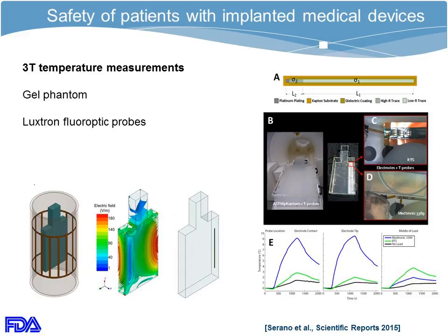It provides an example of how we do that by combining, again, computational models, this is a model of a phantom in a coil with the MRI, and experimental measurements. Computational models by themselves are pretty much useless unless they are somewhat verified and validated against experimental measurements, with a given uncertainty analysis associated with both the numerical simulations and the measurements. And we're working on what the parameters are, and how you can do a validation of a numerical model.